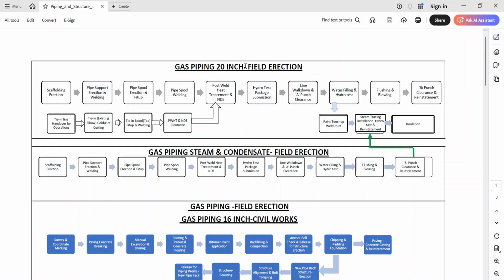Air blowing is kind of drying your piping system, where you'll be using the compressor. From the compressor, there is a separate bar you need to maintain for doing this air blowing as well. You pass the air inside the piping system. Then at the end side, the flanges may be closed, and sometimes you will build the pressure and release it off. So we keep on doing that blowing. For that also it will take some duration.